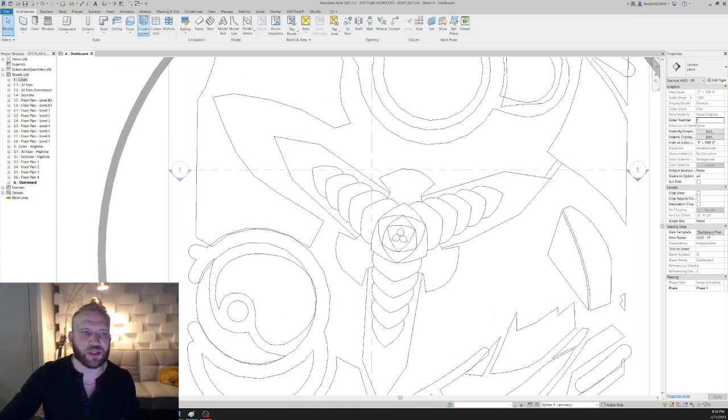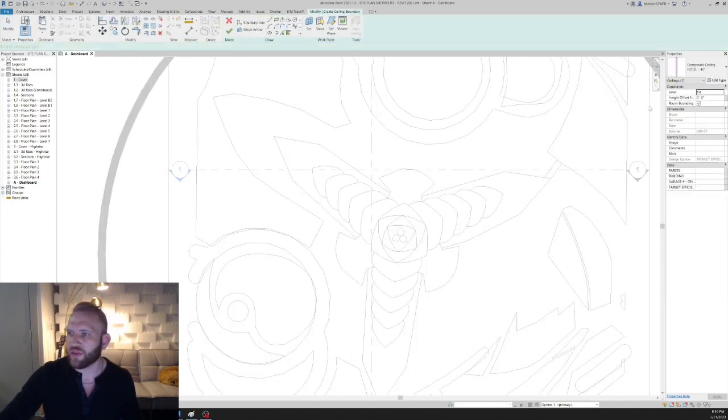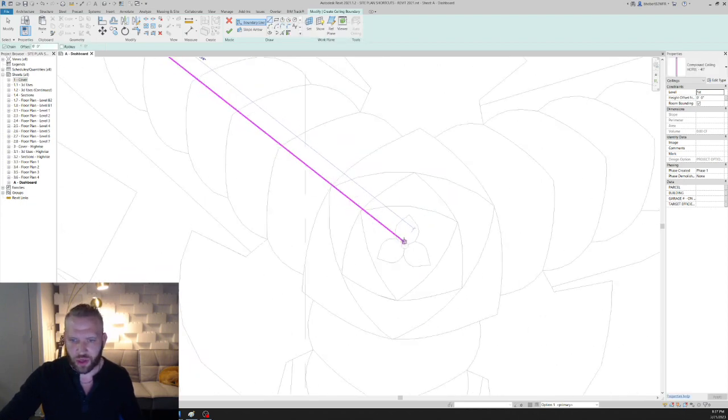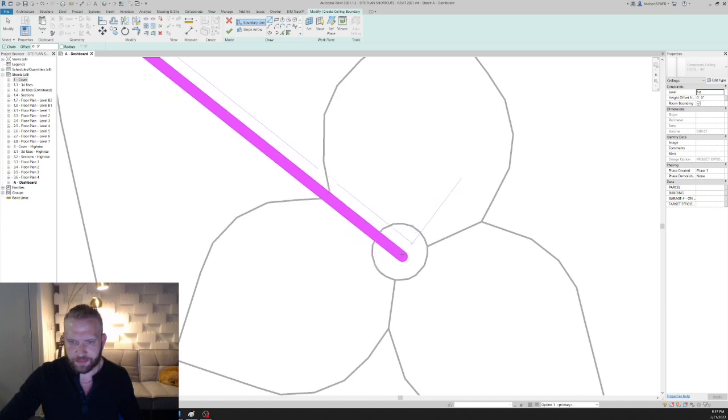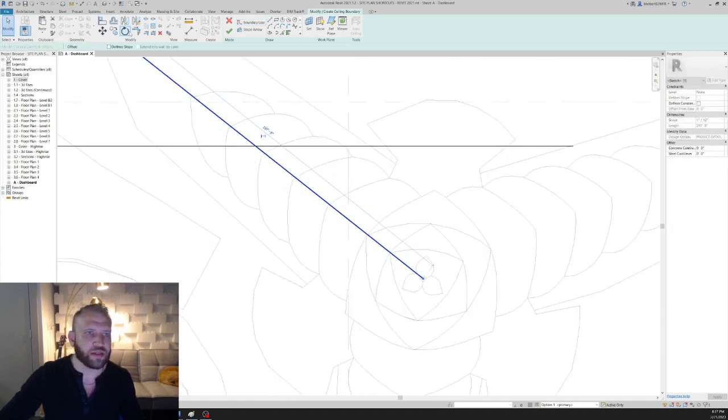Now, using site plan shortcuts, we use a couple little tricks here that you're not going to find anywhere else. In fact, you'll find it nowhere else on the planet probably. I use ceilings to create these massings because I want things super fast. So what I'm going to do is draw my first axis, and we're going to just throw it in there like that.